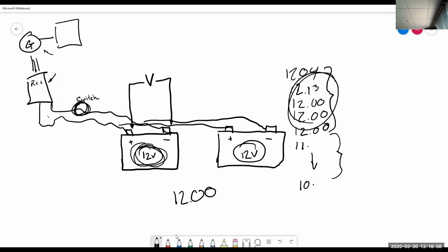All right. What happens if you reverse it? You go red to black, black to red. Does your voltmeter blow up in your hand? What does the voltmeter show then? Negative. It's just the straight negative. There's nothing wrong with going the opposite direction when you're reading voltages.